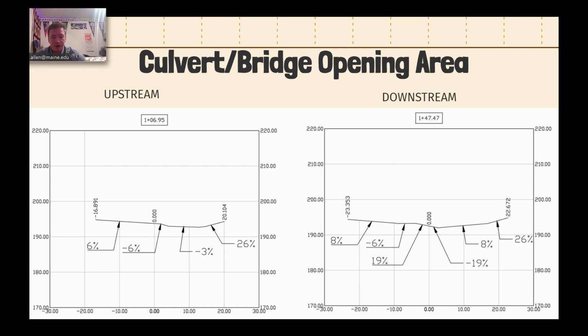The average of this value was used in our design along with the average cross-sectional area. Taking the average flow rate, which was 127 cubic feet per second, and dividing it by the average cross section of 33.6 feet squared, we get a flow speed of roughly 3.8 feet per second.